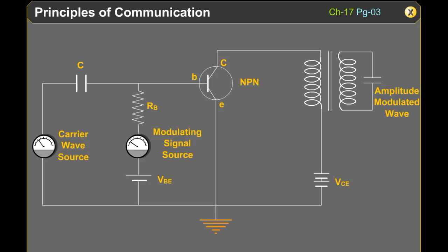At the receiving end, the signal is weak due to attenuation in the channel. The receiver must amplify the received signal first. The signal is usually accompanied by lots of other unwanted signals or noise. Only the desired signal is selected and others are rejected by the receiver. Demodulation is performed in the receiver to recover the original modulating signals.